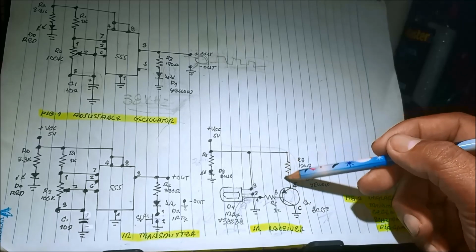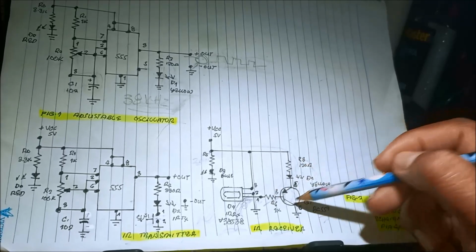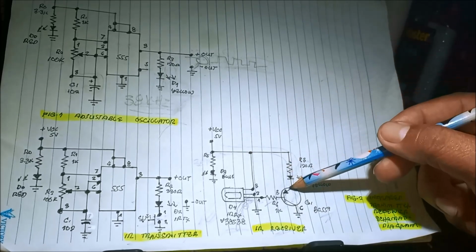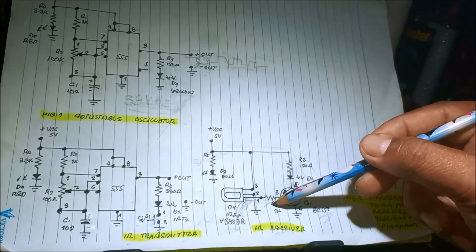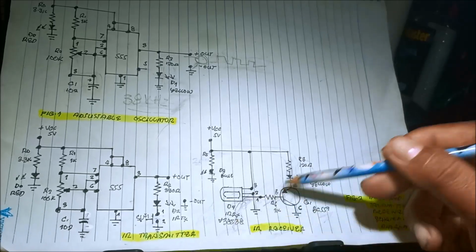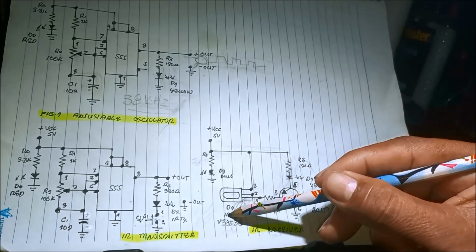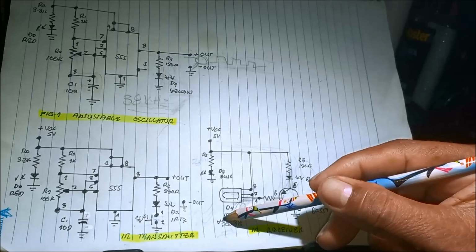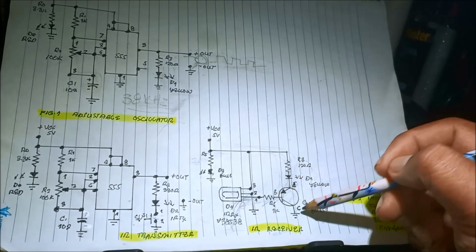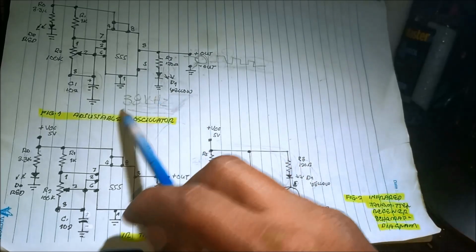It will forward bias this transistor and will turn on this LED. This is a PNP type. Current flows into the emitter, and then to the base, biasing and turning on this transistor, then to the ground, so the current flows in this direction to the sensor. So it means we are sourcing the signal, and then it will turn on this LED once we press the button, or when we modulate at 38 kHz.